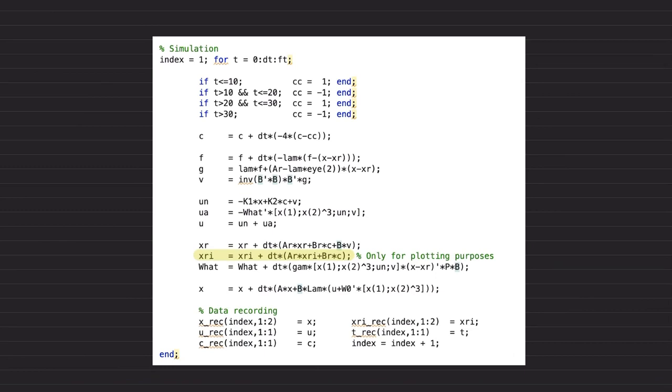As some insight, this is the square wave, basically looking like this. Instead of directly applying it like this, I just filter it. I apply the filtered version of the command to the actual system because we really don't want sudden changes in the dynamics, so as to achieve a smoother behavior.